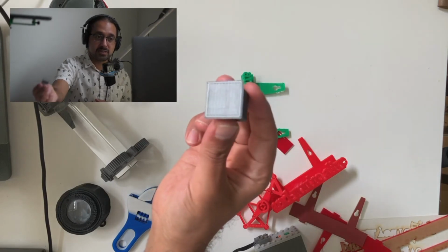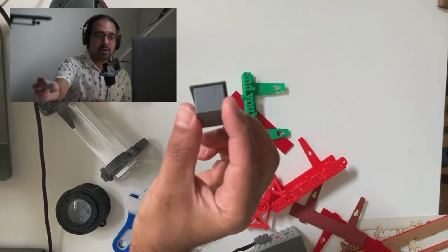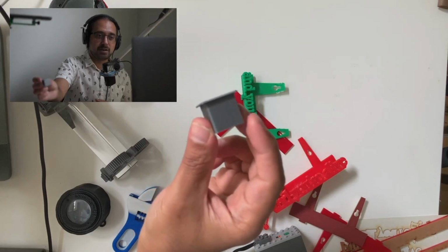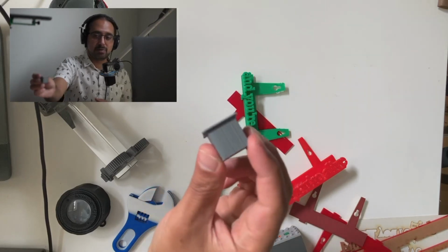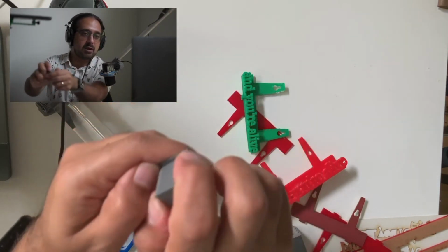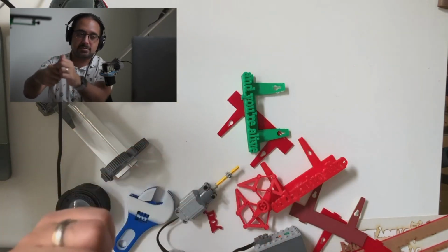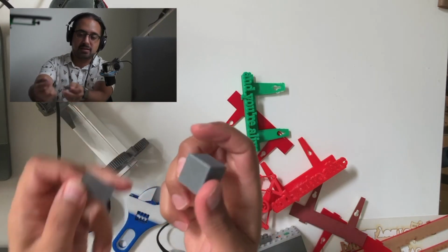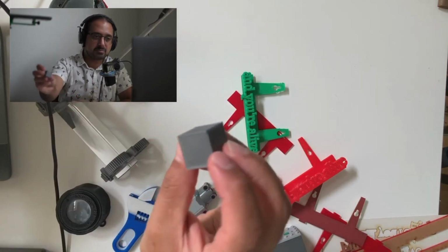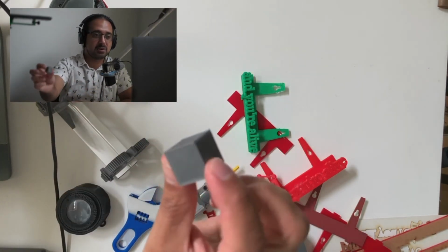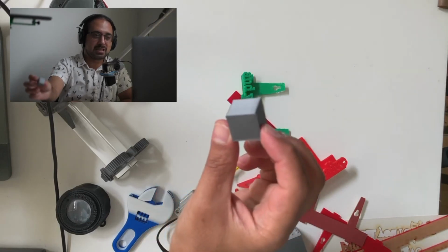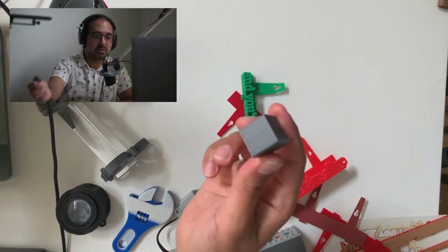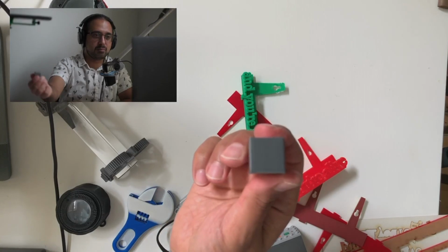I'll go into it a little bit more next week, but you can see at the bottom that it's printed out this thing called a raft. What the raft does is prevent the print completely sticking to the actual print bed. And you can take the raft off to complete the design. So I'm going to try taking it off here. It just snaps off. And then you can see that we've got this fairly dimensionally accurate 25 millimeter cube. That's the result of the print.